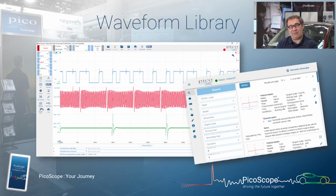And it's that comparison of a known good waveform against a vehicle that you're trying to diagnose that is hugely valuable to you as a technician. So is that capture waveform and compare. There it is, that's what we see.